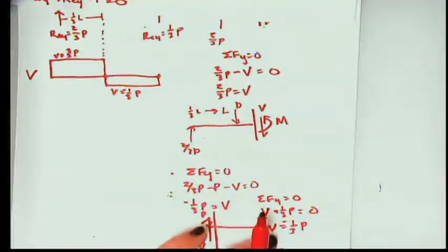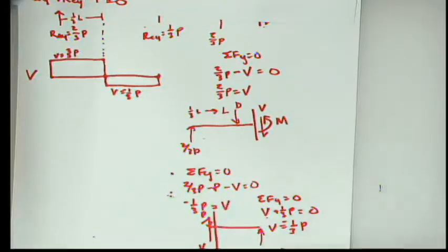That if you cut from the right or you cut from the left, you're going to get the same results on a shear moment diagram. So what this does is it organizes the shear, shows you where it's going to be the maximum, shows you where you're going to have discontinuities, and then, like I said, it also shows you that you can work from one side or the other. I tend to work from the left to the right when I do these types of problems, but if there's a whole bunch of complicated stuff over here, I'll definitely start from the right and cut on the left. Absolutely.